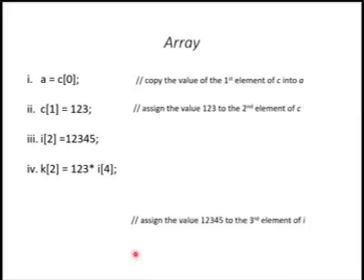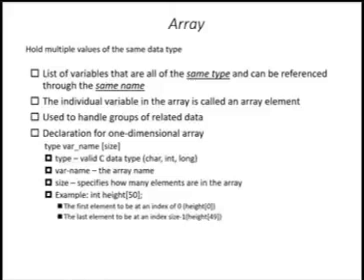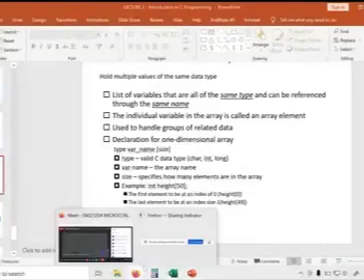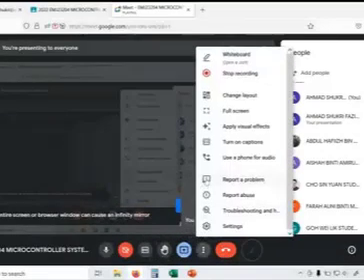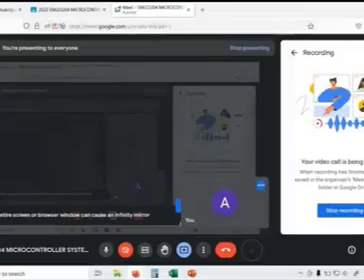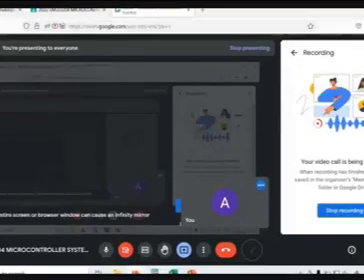If the value of port B is 15, or 1111, all bits are high, so you begin turning off every bit in port B. If you connect the circuit using LEDs, it is actually blinking. All of port B will be turned on and also turned off, and then wait for 500 milliseconds, and then you do the rest by checking the condition here.